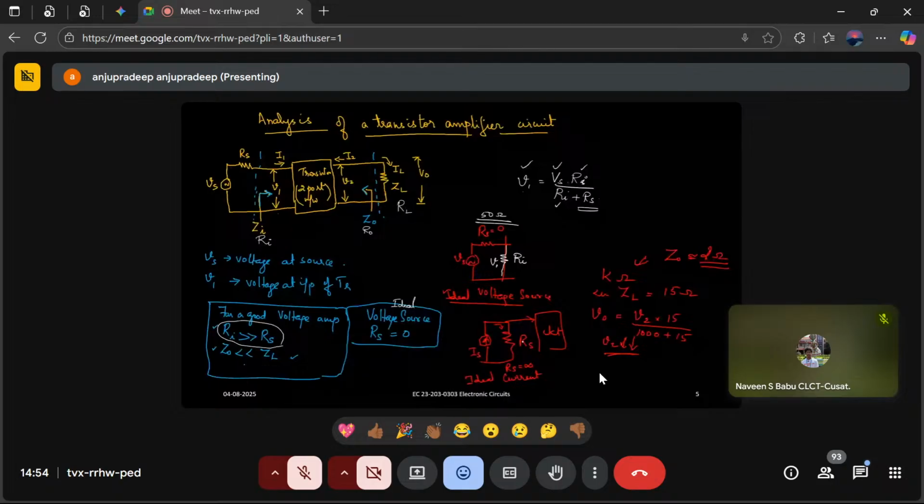So if you want to get maximum current from the source, the input impedance of the circuit, when you are using a current source, should be as small as possible. And if you are designing a source, make Rs as large as possible.